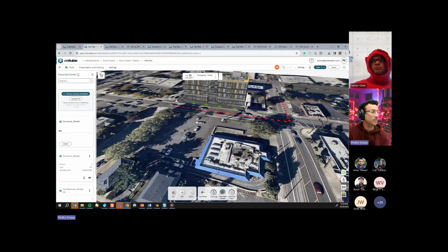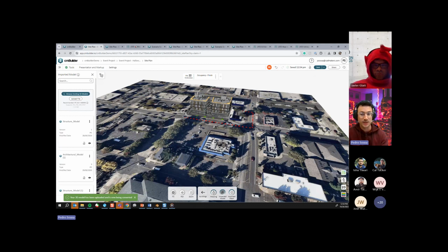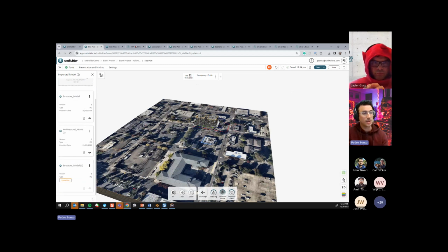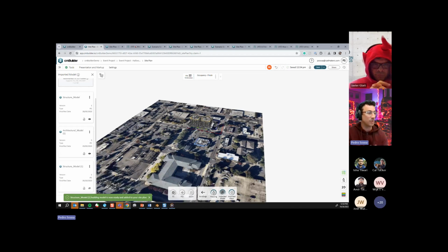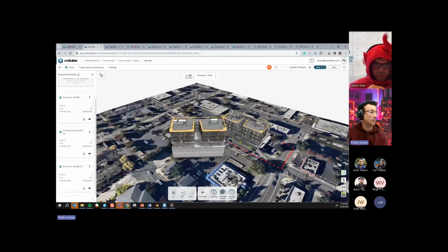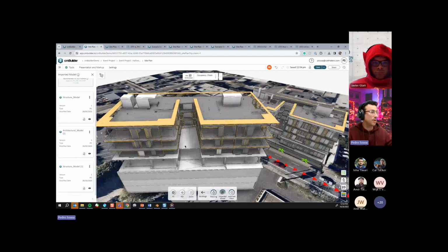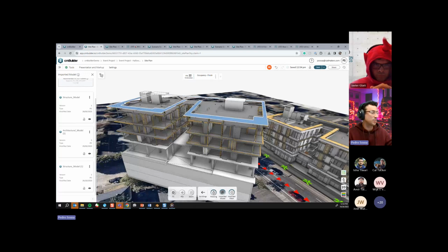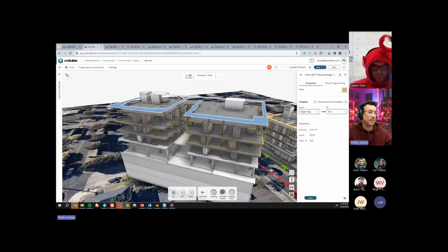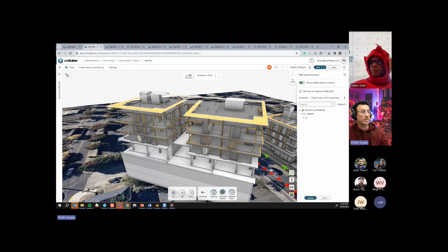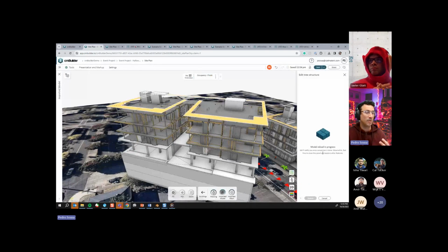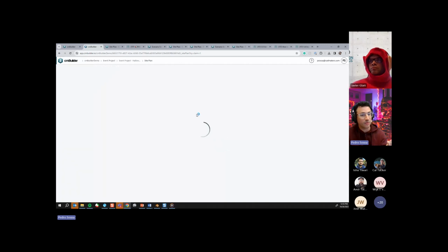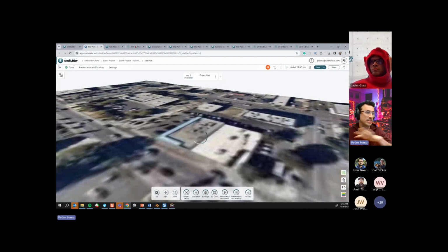And when you confirm the upload, basically we are going to upload that same model, but without all of those parts. Cool. Let's say that by mistake you imported a model with those parts and you won't use them in your view. Basically you can take the new model that I imported over here, and I can select the parts that I don't want in my 3D view. Let's say this one, for example. I can select this part and say edit model element. Then I can click on this new function over here at the bottom, remove model element. This will remove the geometry from this scenario completely, right? So when I update this, it will take a couple of seconds, and the view will refresh, and now we have a model version that does not have that part.